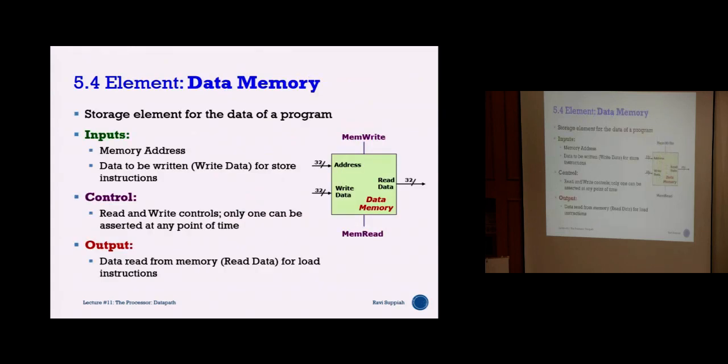Okay, so the concept is the same. I present an address, and in that address, if I'm going to read data, I must trigger the memory read pin. Then I'm going to read the data. If I want to write data, then I must trigger the memory write together with the data that I want to write.